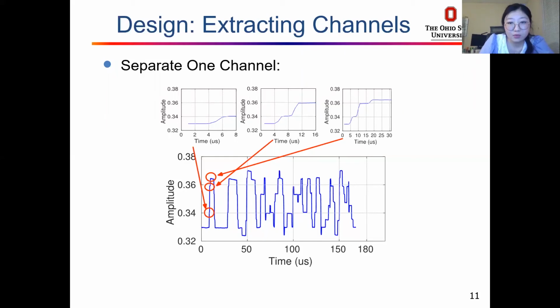Before the data stream of the first tag arrives, the reader only receives 0 bits. After one tag joins, the signal steps to non-zero bits, and when the following tag joins, the level of the non-zero bits changes. Hence, we can obtain the clean channel of the first tag, since there must exist a time when only the first tag is transmitting.